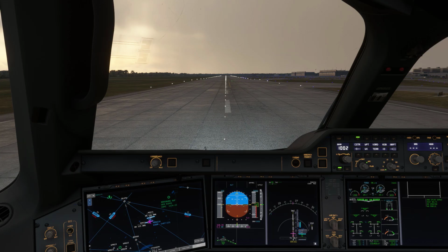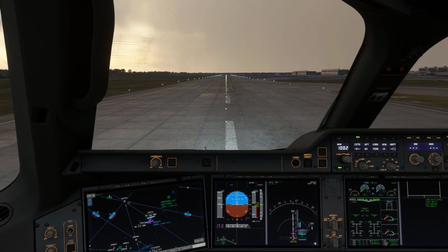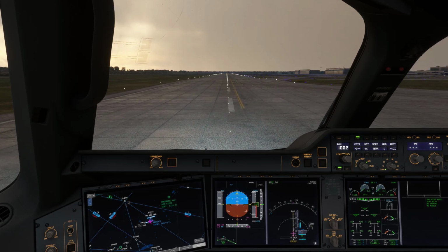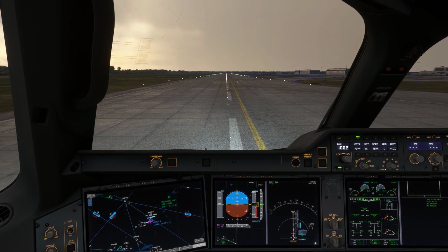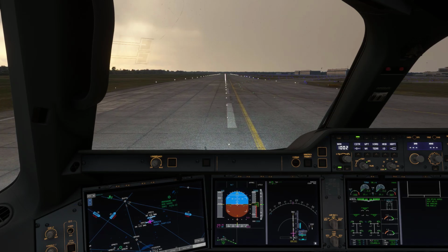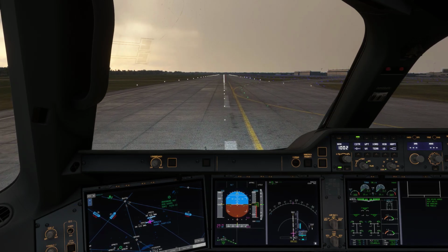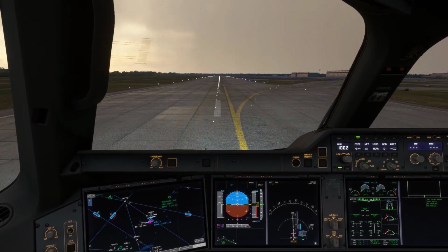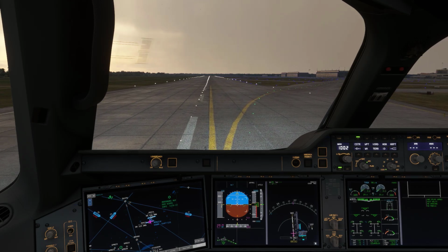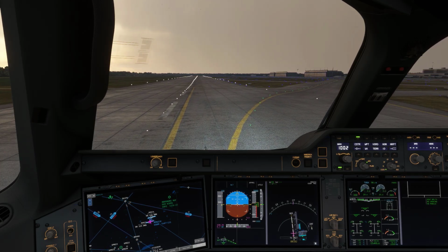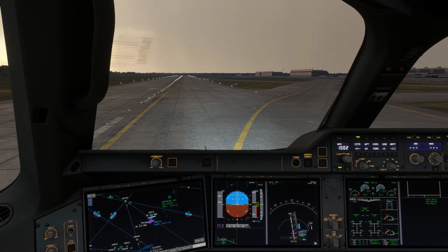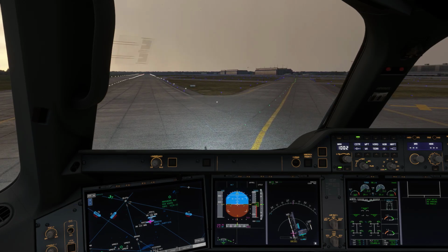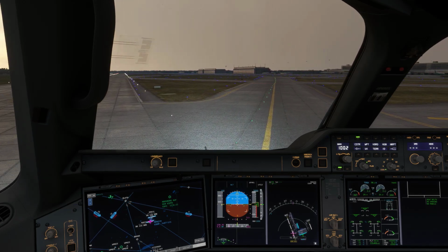Let's exit. The next exit. Good. That was a, well, so-so landing, because the airplane was not level. Let's exit there. Spoilers retract. Disarm. Flaps up. And there we are in Munich. I don't want to bore you with the taxiing back to the gate.